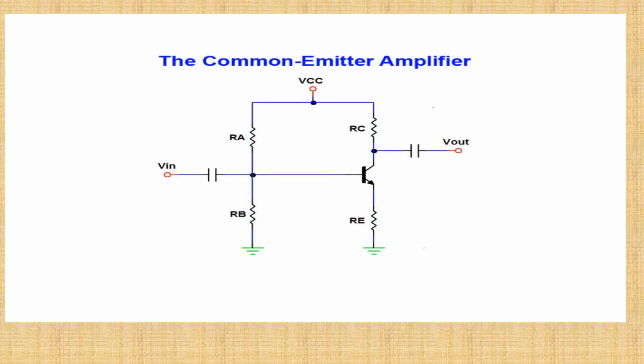In addition to these core circuit elements, we are also using 2 coupling capacitors, which effectively block the DC element from the input signal as well as the output signal. The signal appearing at the input to this circuit is amplified and phase shifted by 180 degrees.